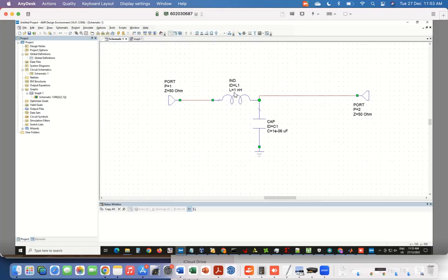But remember, we have talked about parameterizing this in terms of two other quantities, which is actually the resonant frequency and the characteristic impedance, right? The ratio of L to C. This is not a transmission line, but it's an LC section. So we can also say it's either the product of LC and the ratio of LC. You can see that the resonant frequency part will be related to where the cutoff frequency is, right? But the ratio of L to C, which is the characteristic impedance part, will do something else.